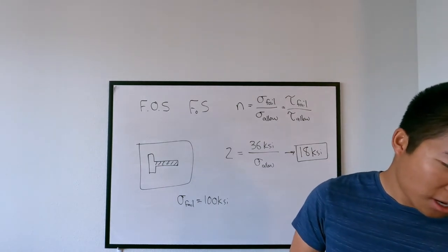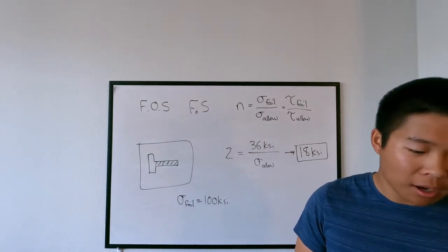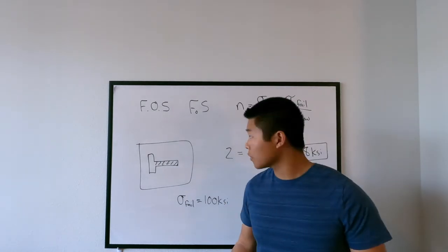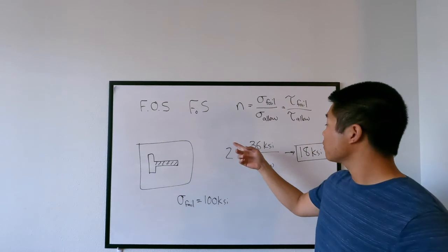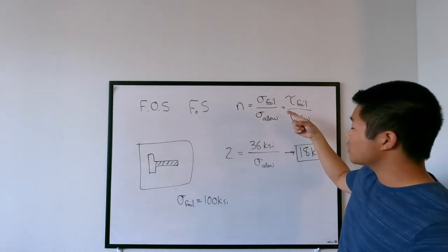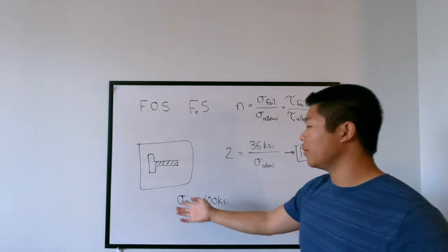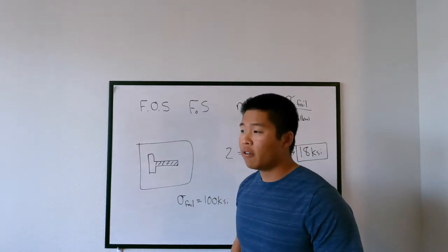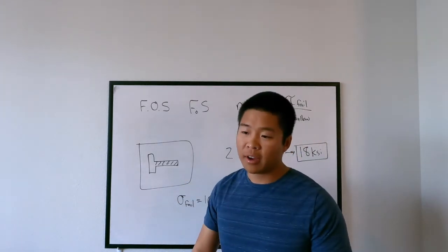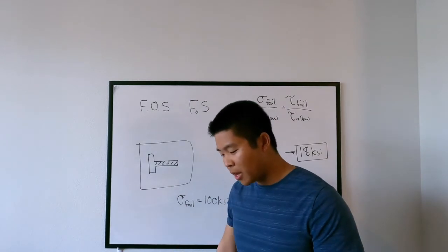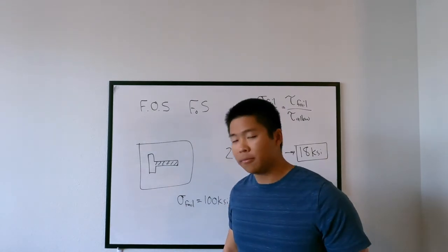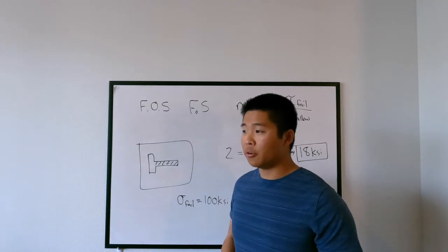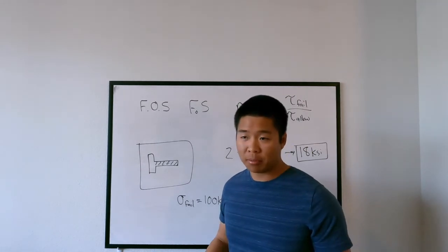So the question is, how do we find the allowable force and weight? Find out what will cause failure. Essentially, if we have this plane, we know that if we load the plane with 400 people, in a simplified case, it's going to fail. Of course, this is extremely simplified. If we want a factor of safety of 2, then we would only put 200 people on the plane.